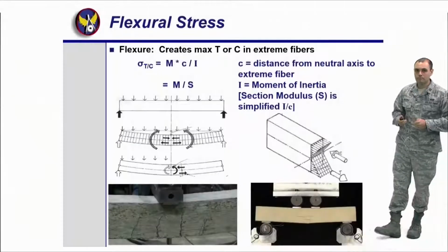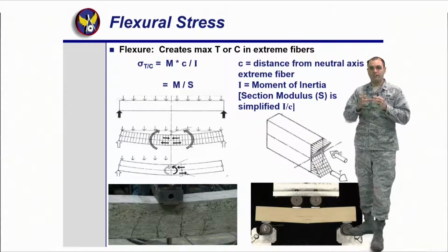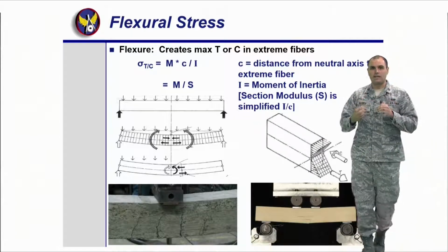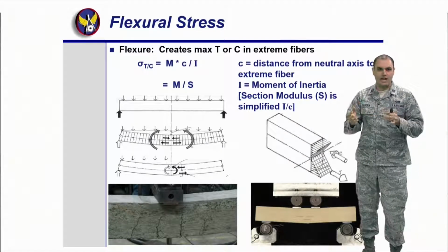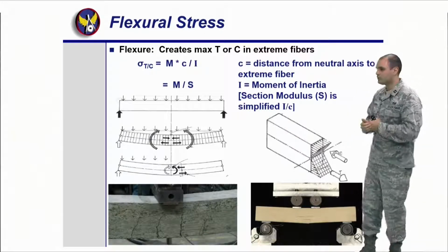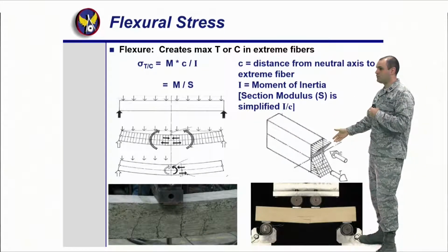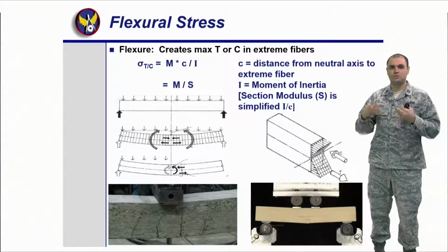Cool. All right, the other one is talking about flexure stress, right? So flexure is we're trying to bend the beam, right? And that's where you start seeing the failures in the bottom of the beam. Flexure can happen in columns, walls, but usually beams is the easiest way to explain how it works. So when flexure happens, you get to see this kind of triangle occurring. We have a compression section and a tension section. What do I mean?